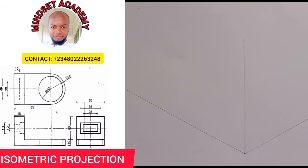If you look carefully, we need to get the entire height, the entire length, and the entire width. Now, in this diagram, the one in the middle is always the front elevation, right? So this is the front elevation. To get the entire length, since it's not here, you check from the top one.